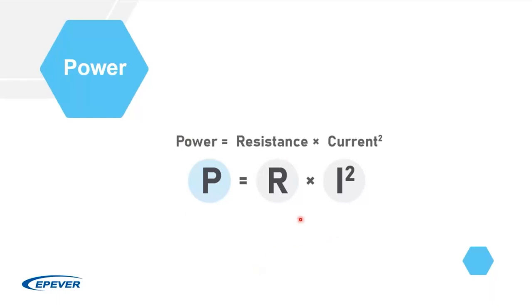So we are opening a window to this concept that if you have long wires in your installation, you're losing power somewhere, and this is going to be a big problem in your design. Every single component of an off-grid system is crucial and important, and should be chosen based on certain reasons, and should be designed in a way that you have the minimum loss in your system so that your efficiency is high.